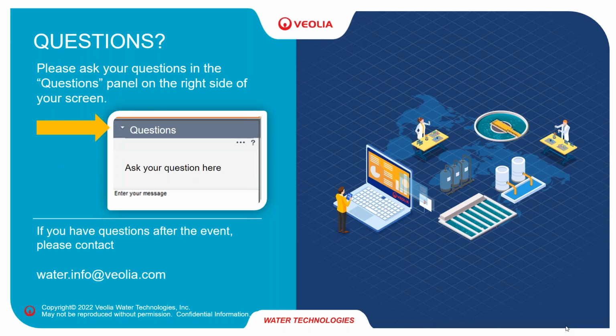Okay. So upstream of the filter, the requirement is a primary clarifier. It's not that solids themselves, in terms of concentrations, are so much of an issue, especially for diluted water. But experience showed that if you don't have this primary clarifier, you'll end up with surface clogging of the filtration bed. That's probably linked with toilet paper and fibers from the wastewater. So the primary clarifier will remove this fibrous material and allow the TSS to penetrate deeper in the media filtration bed.